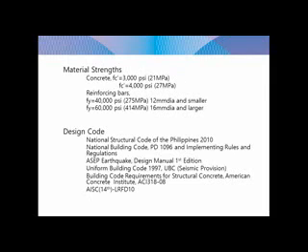We have the design code. We use NSCP, or the National Structural Code of the Philippines 2010; NBC PD 1096 Implementing Rules and Regulations; ASEP Earthquake Design Manual, First Edition; UBC 1997 for seismic provisions; for structural concrete, the American Concrete Institute ACI 318-08; and then the AISC 14 or the LRFD 10.